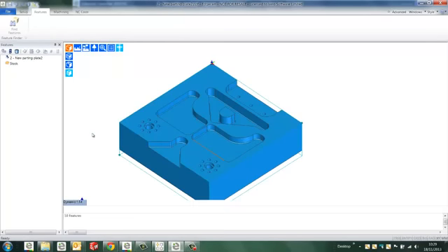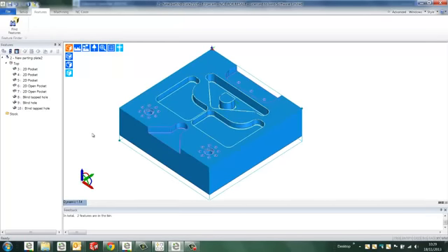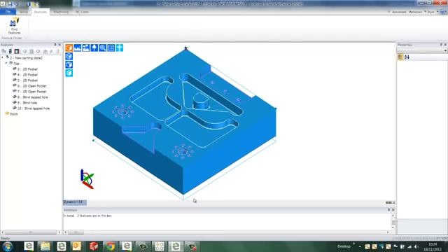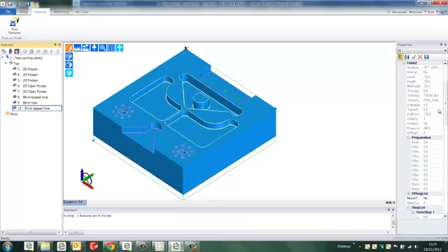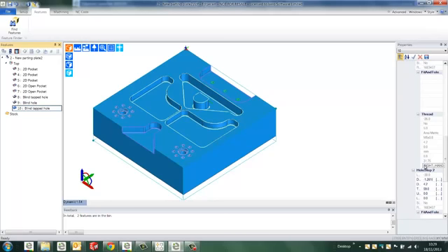We spoke about the properties and attributes during the PowerPoint presentation, and what I'd now like to do is just share with you some of those attributes by opening up the properties window on the right. If we select, for example, the blind tapped holes, we'll see down the right here we get a full complement of manufacturing information. We can see we've got the levels, the depths, we've also got the tapping drill size, we've got the threading information, and this is really valuable information for when we start to execute the automation inside the planning board, or indeed the machine feature.